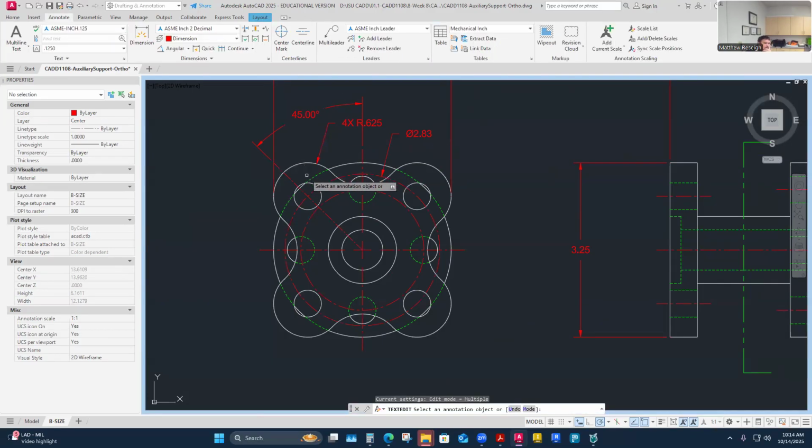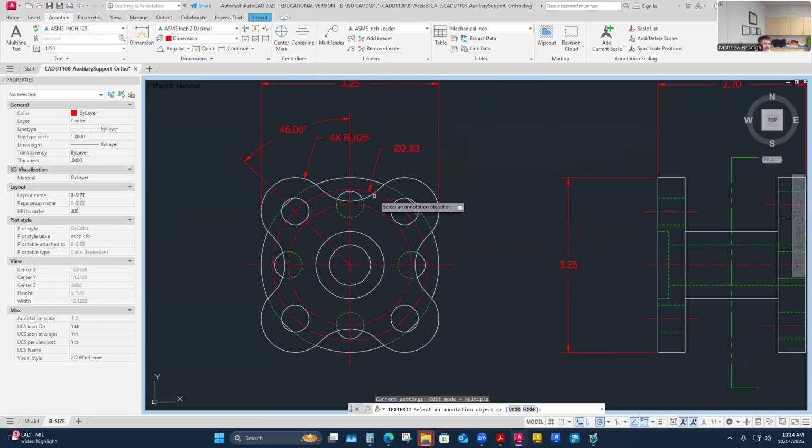And then what I actually have going on is a need for one more angular dimension, which is going to be from here to the next one. So I'm establishing a from here to there, this being the control, vertical center line, and to my feature that I'm actually looking to locate. And if there's four of them, I'm going to say from here to there 4 times at 90 degrees. And that's going to get me back to where I started from.